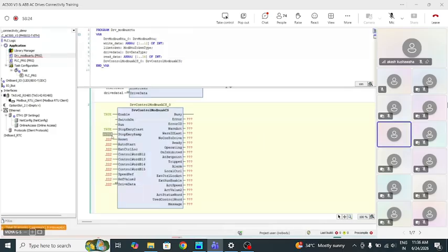If you've already done Modbus communication with ABB drives, you would know they give a control word in a sequence like 1142, 1143, and 1151 in decimal. 1142 is for ready, 1143 is for stop, and 1151 is for start. Exactly those commands are designed in this block.